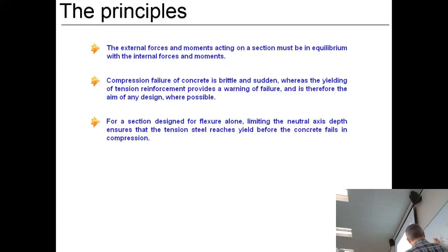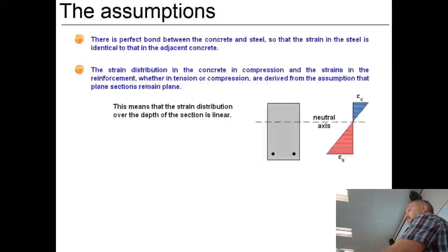So the whole point is that you'll see how we'll try and mess around with this neutral axis location to try and make sure that the steel is going to fail first, or yield first.